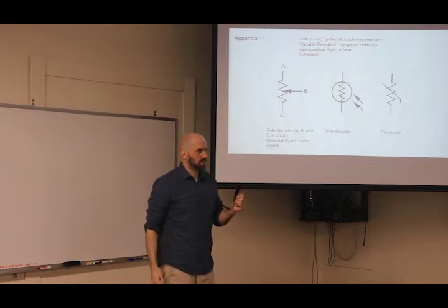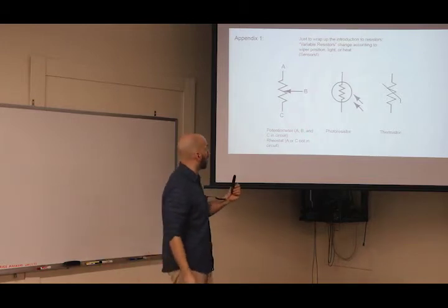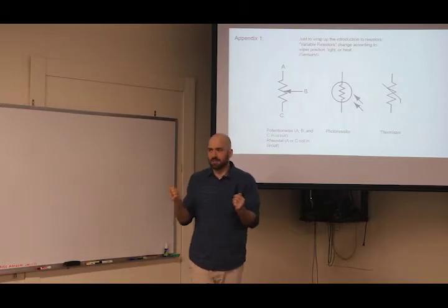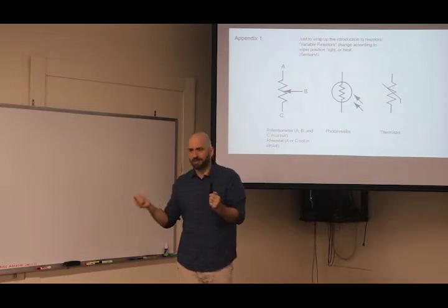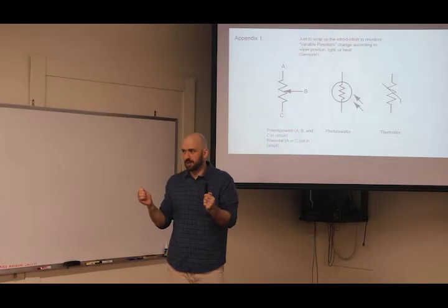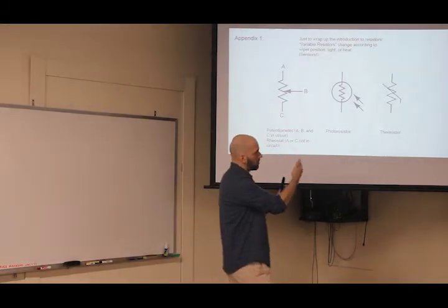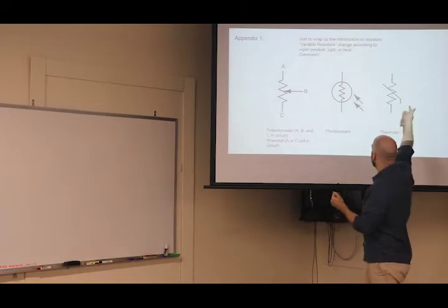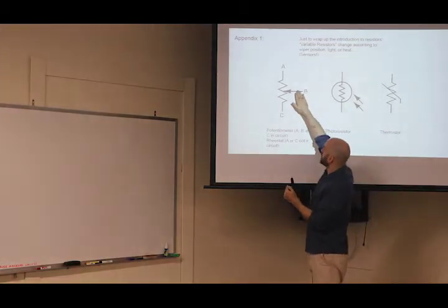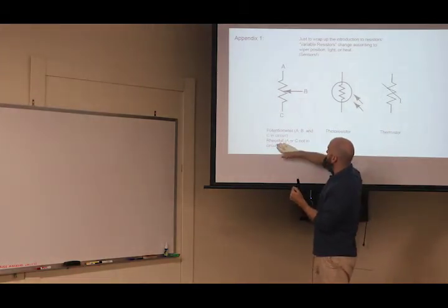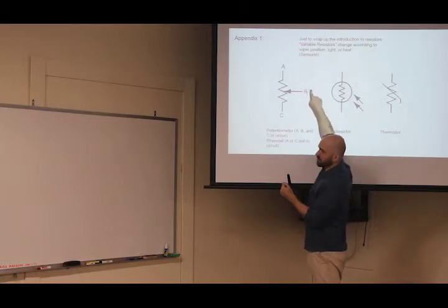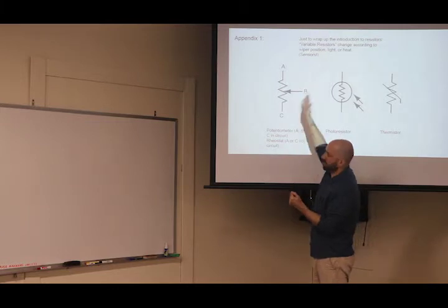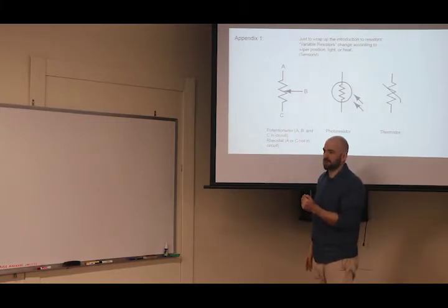Because we talked a lot about resistors, and we saw a lot of resistors in the circuits today, I should mention that there are also variable resistors. You buy a 10 ohm passive resistor off the shelf, and it's always going to be 10 ohms. There are ways that you can vary the resistance depending on position, light, or heat. For position, if you're connecting this, which is called the wiper, and one of those, that's called a rheostat. If you connect them all, that's called a potentiometer.